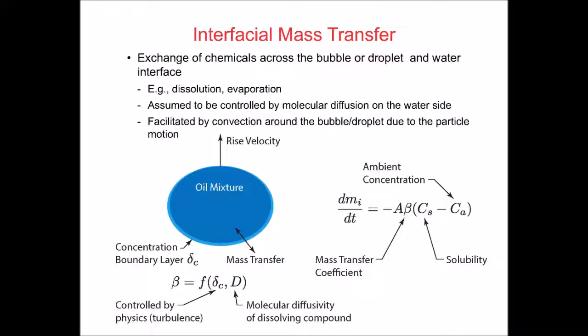And so this mass transfer coefficient tries to summarize the effects of the chemical boundary layer and keeps in mind the fact that molecular diffusivity at the gas-water interface is the rate-limiting step. For gas to get out, it has to overcome molecular diffusion rates in water at the gas-water interface because there isn't any turbulence right there touching the gas bubble.